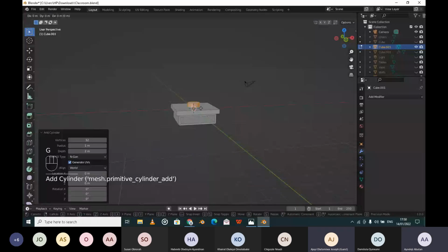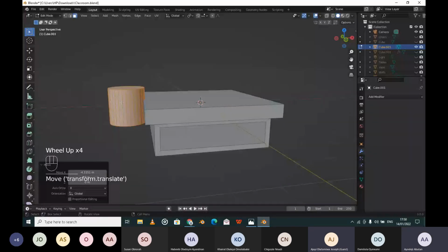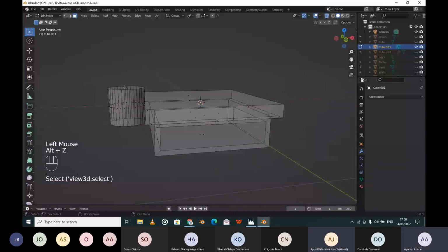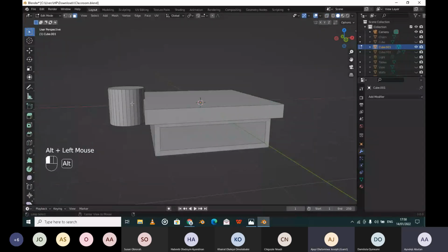One way to fix that is to select your cylinder completely. Use Alt Z to go into X-ray mode and select every single face of your cylinder. Do you understand that? Yeah. You can use Alt. Hold down your Alt key and click on your face. It should select all the faces around the cylinder. Then hold down Shift to select both the top and bottom face.